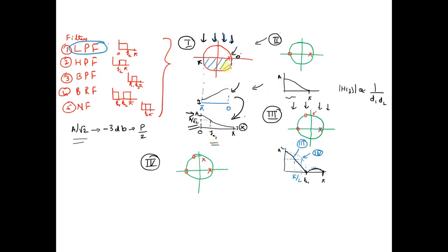Now, in the second way, if you see over here, there are some frequency components which will be passing through the system. Now, if you use this, what happens? This same frequency component will be repeating itself. So when that happens, the high frequency components will mingle up with the low frequency components during the repetition. Now that would result in the aliasing.